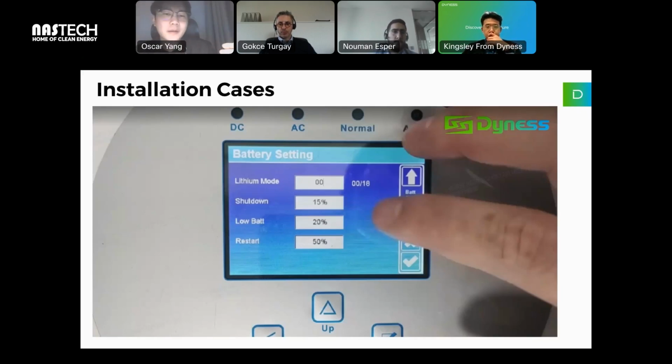For the inverter, there are many other modes. For example, there is also battery voltage mode. This mode will track the voltage of the battery. It will not communicate with the SoC of the battery. In this situation, you cannot monitor the SoC. You cannot see the current. You cannot see anything. You can only see the battery volt out of the battery cell.